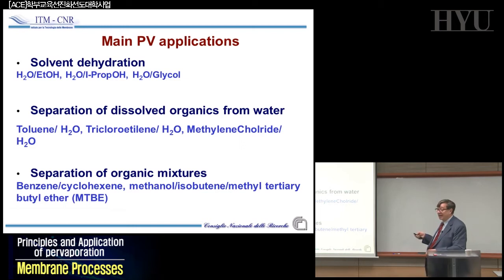It's done with glycol, a lot of ethylene glycol, etc. That has to be recovered. After you treat the solution and recover it, it is done with pervaporation. There are a lot of plants around where you can reconcentrate and separate water from glycol using pervaporation. This is the most industrialized application today.